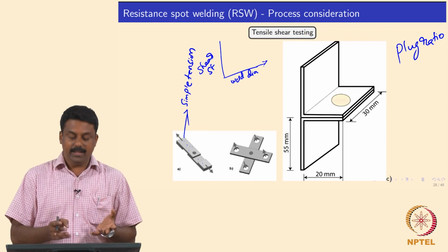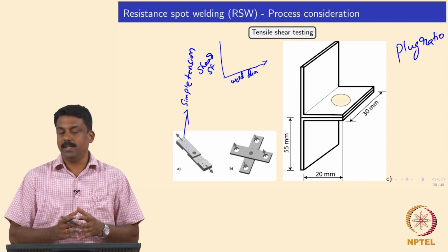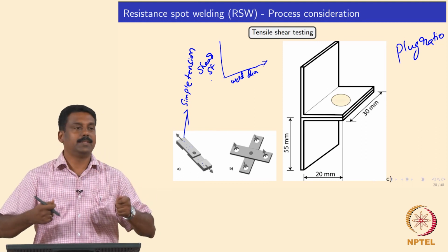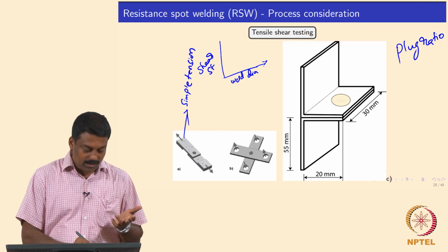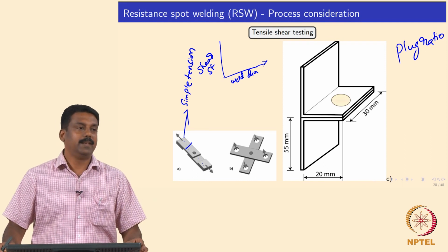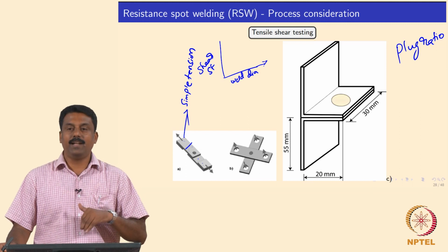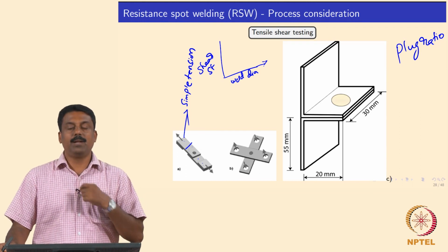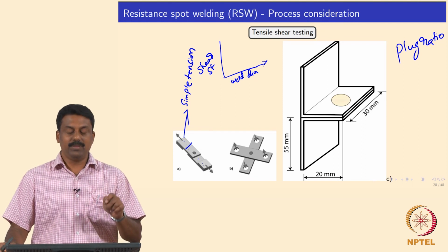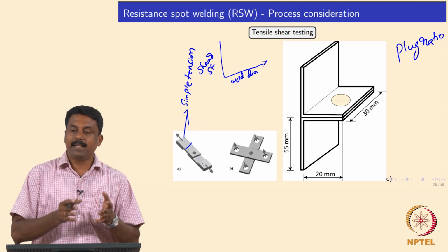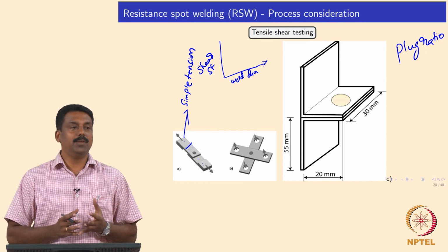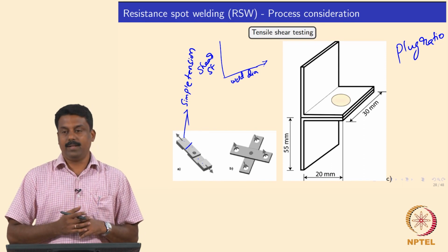So, in order to clearly quantify the weld properties, we also measure the strength required to break the joint, but this break can also happen elsewhere, is it not, in the base material. But then that is not real identification of weld metal property. Okay. So, we identify the strength required to break anywhere plus the plug size, right. So, both combined would give us the mechanical properties.